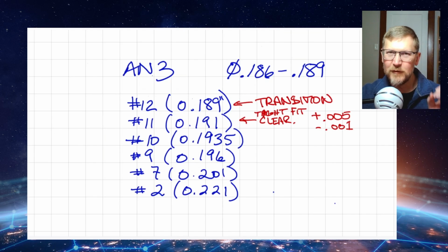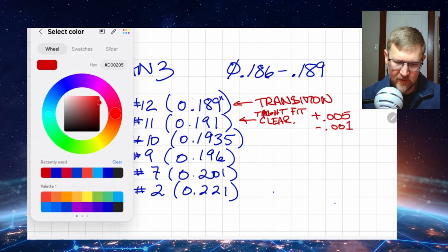Now, if you're having a super tight hole and it's got to be very precisely located to another one, if you machine these parts separately and that hole comes in just a little bit to the right, well, you've already eaten up all your tolerance. So you need to make sure you're accounting for the tolerances of the assembly and the manufacturing techniques as well. And so we're going to have to potentially add more flexibility into the design to accommodate more manufacturing tolerances.